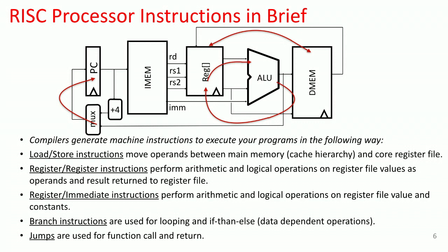It's conditional operation. And the conditional operation happens by modifying the value that's in the program counter. Normally, the program counter just points to the next location in the instruction memory, because the normal sequence is to just do one instruction after another. If we want to branch to somewhere else, to jump around some section of code, or to loop back to the beginning of the program or some other section of the program, we need a branch instruction to change the program counter value. And that's what the branch instructions are for.